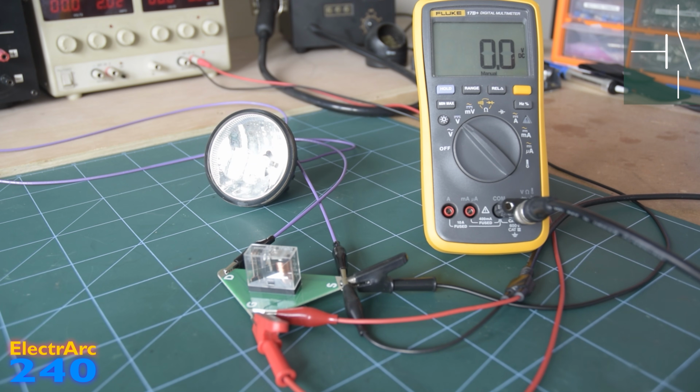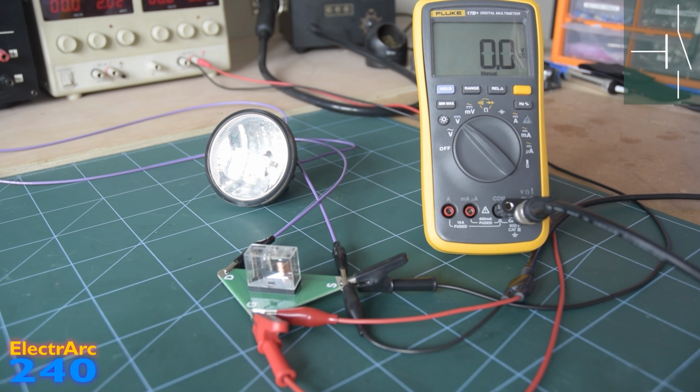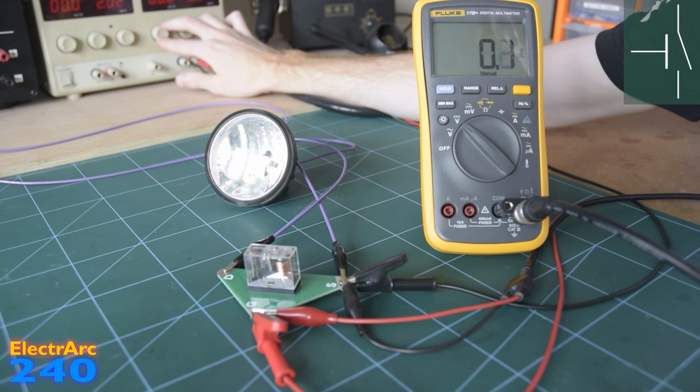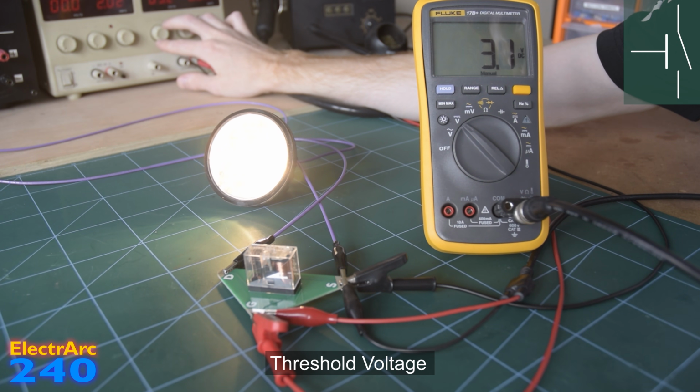Now so far I've just been applying either 5 volts or 0 volts between the gate and the source. What happens if we apply a different voltage? Well, let's take a look. This multimeter is connected so that it's measuring the gate source voltage, and I'm going to slowly turn it up. As we can see, nothing happens until we reach what's called our threshold voltage. And that's the voltage you need to apply between the gate and the source to turn the MOSFET on.